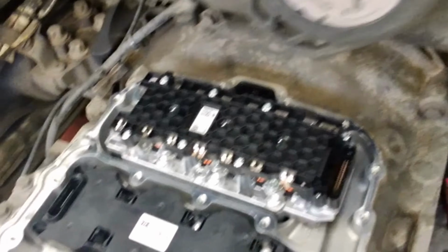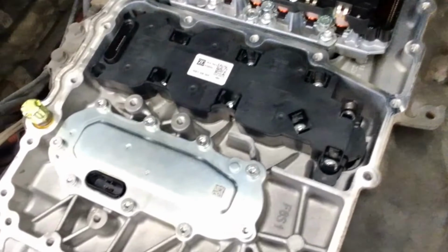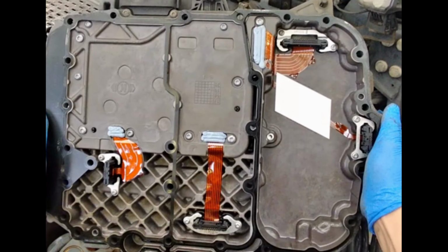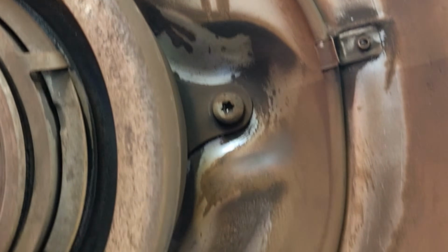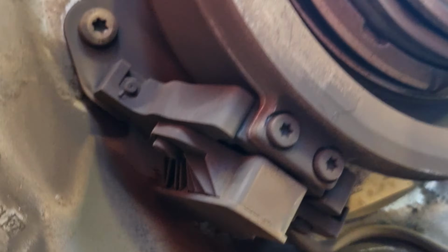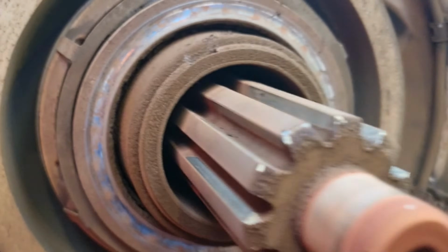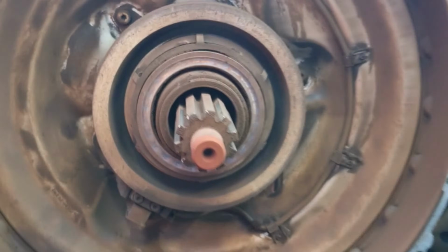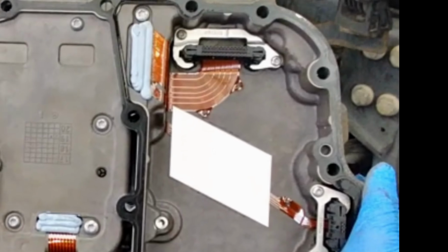So we have three modules here and we can go through what they are and the functionality now. First up at the front we have the clutch position sensor. This measures the clutch travel and is used for determining the clutch open, clutch close and transfer point. It is connected with the fly lead to the Traxon ECU at the top. The clutch actuator wiring loom is part of the clutch actuator. The clutch actuator controls the clutch based on a measured position from the position sensor.